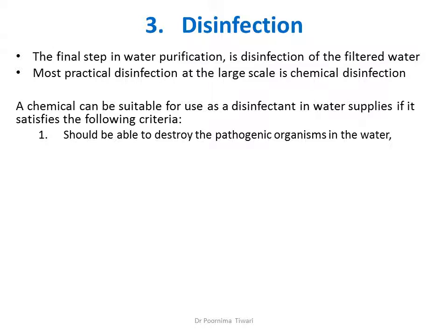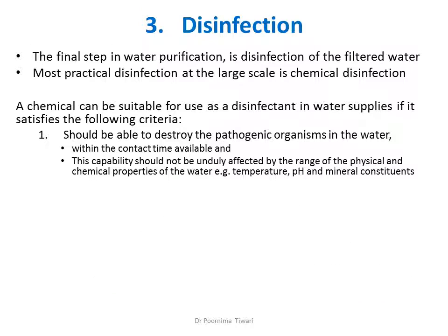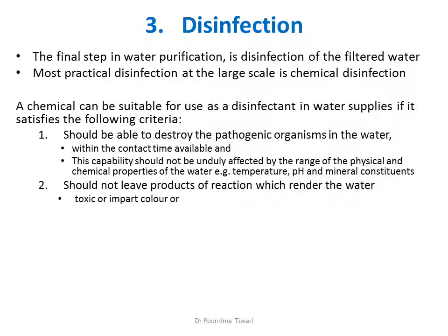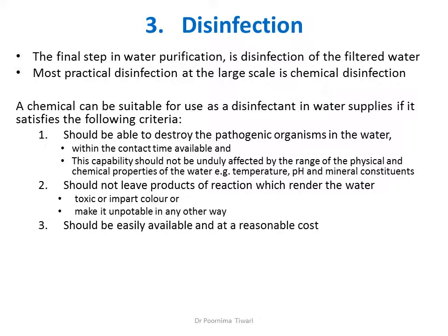The chemical should be able to destroy the pathogenic organisms present in the water within the contact time available, and this capability should not be affected by the range of physical and chemical properties of the water. The chemical should not leave products of reaction which render the water toxic or impart any kind of color or make it unpotable in any other way, like altering the taste too much. The chemical should be easily available and at a reasonable cost so that we can continue disinfecting the water supplies.